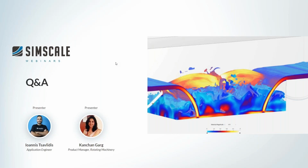So typically, a best practice would be to have at most 3 degrees per time step. We shouldn't let our machinery rotate by more than 3 degrees within a single time step. We put this information inside so that if you try to put in a larger time step, we do some calculation in the background, calculate the rotation speed, the degrees and everything, and we give you a warning: look, this time step is too big. Maybe you should consider lowering it a bit if you want to get the best result. But this is just a warning. Of course, if you know what you're doing, you can skip this warning and just run the simulation.